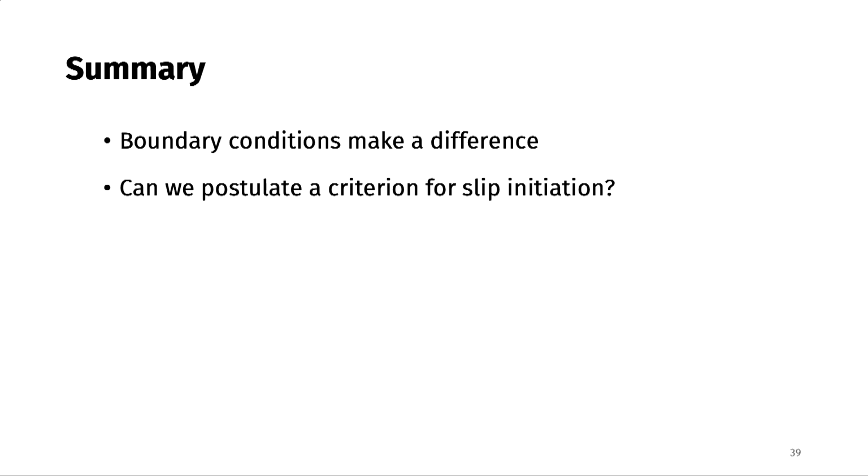Now, this begs a question: can you postulate a criterion for slip initiation, right? Just like I said, the criterion for crack nucleation is a far tougher problem than the criterion for crack growth, right? If you have an incipient crack, you can see under what loading the crack will grow. But given a loading with no crack inside the material, predicting when a crack will form is not very easy to do. And so can you use something like this to give an analogous explanation for slip initiation, which is basically the same problem?